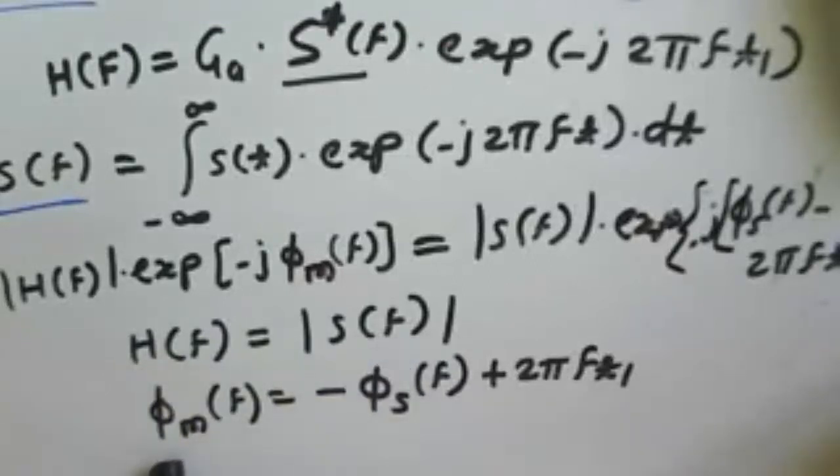But the phase spectrum of the matched filter, phi m of f, is the negative of the phase spectrum of the signal, phi s of f, as well as a phase shift proportional to the frequency.